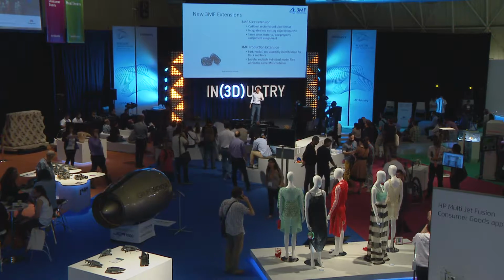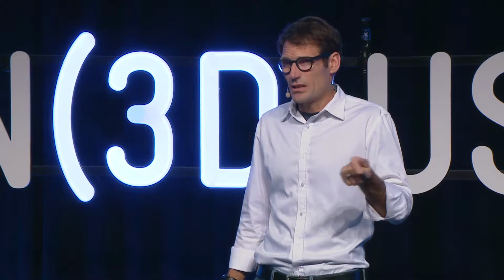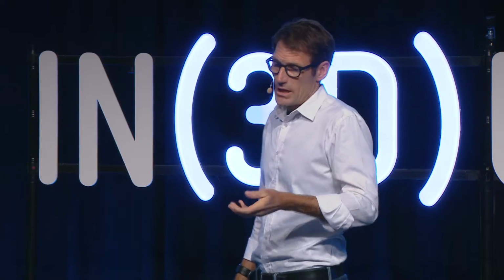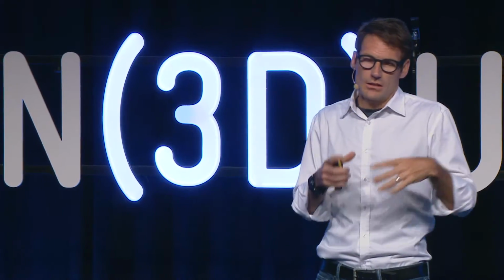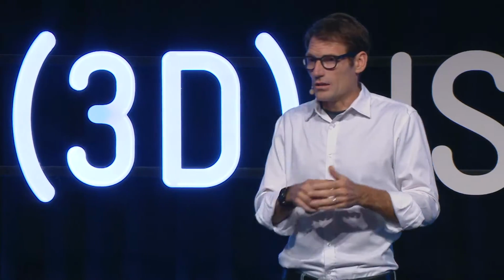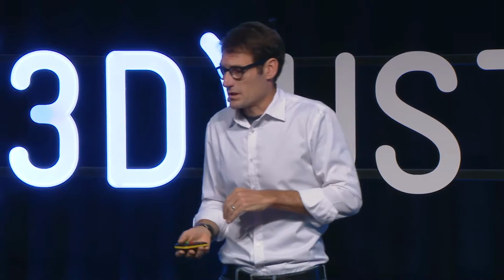One is a slice extension. So most printers operate on slice data today. Our printer does this as well, HP's printer. So the slice extension enables a vector-based slice format. It integrates neatly and cleanly into the existing infrastructure inside the file, so it's referenced as just another object. And then all of the same material and property and color information is basically inherited by that structure. So it's a clean integration, and it actually sits side by side with the mesh representation in the file.